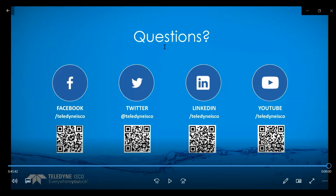I'll take the two-part question here, and I'll start with the first part. Can I use an AV sensor in an invert? Absolutely. With the asterisk there being that the transition from the pipe to the invert and to the outlet pipe is relatively smooth and doesn't have any major changes in profile.